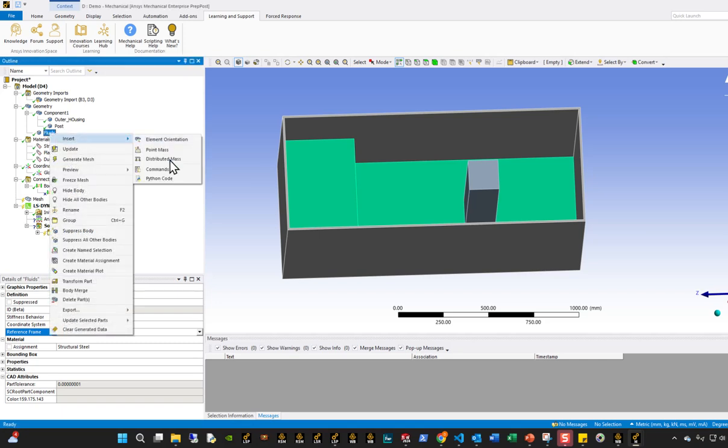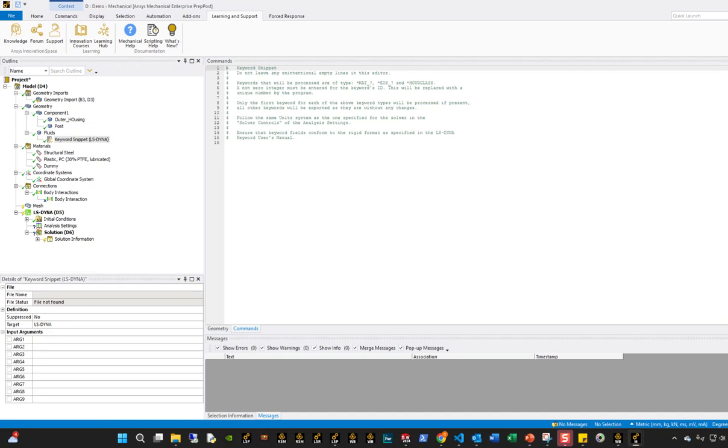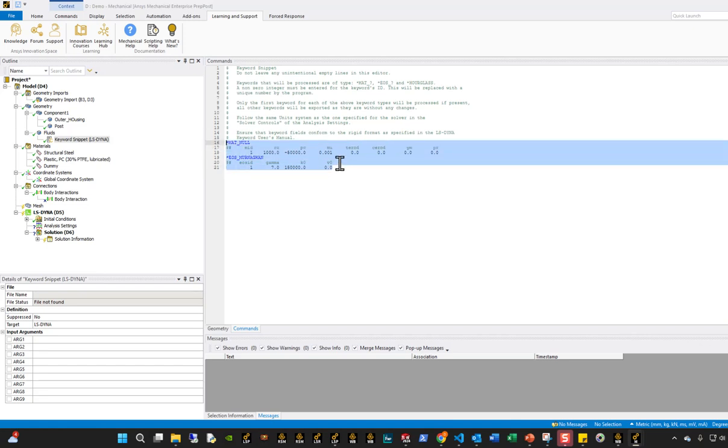Now, from within here, we want to define a few different things, right? So we want to define a MAT_NULL, which is usually what's used to define a liquid material like water, right? In this case, you can see I basically have 1,000 rho here that's sort of indicated. What we want to also generate is an equation of state, the EOS Gruneisen. The Gruneisen EOS basically helps us define the bulk behavior of the fluid. So together, these two things define the material for the water, and these are relatively published material. You can find out in different papers yourself. They usually stay pretty consistent in different papers that I've seen. These two numbers are relatively consistent from there.